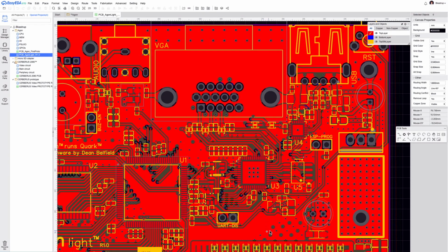That's basically it. Now, the other reason for some other vias is what we call stitching vias. Like these vias here, they are stitching vias. And their objective is the following. I copper flooded the top layer with VCC. In red here, all this copper around, this is VCC.